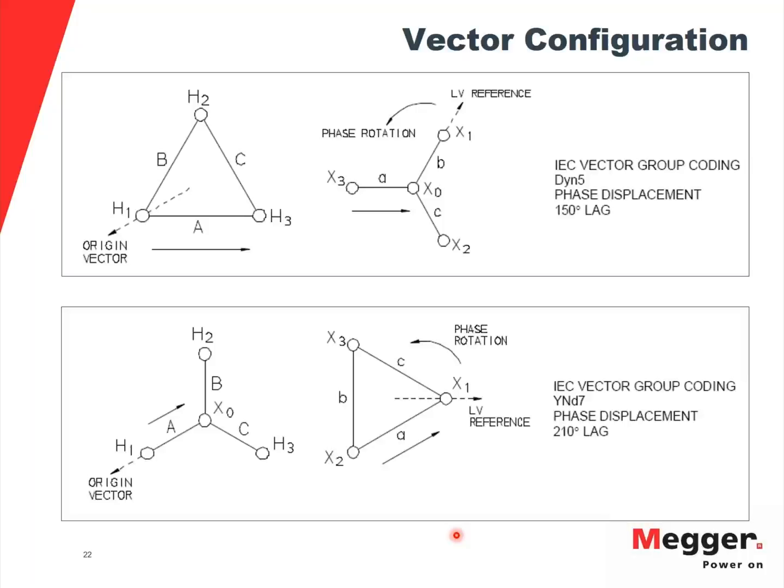It is strongly recommended that you have a piece of equipment, a device that will be able to demagnetize by changing the magnitude and polarity of the DC voltage being applied to your transformer. Other than that, you cannot really see if the unit is properly discharged after any saturation procedure. Anytime you apply a DC voltage, you're creating some energy in the winding that you would like to discharge.